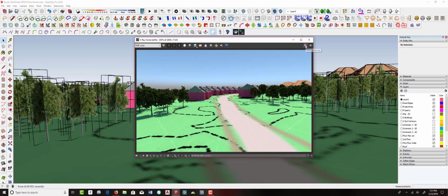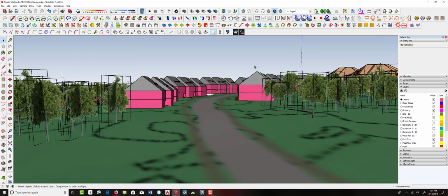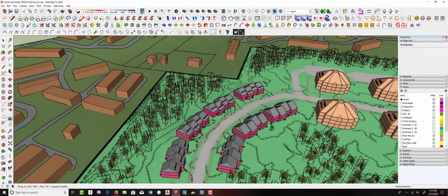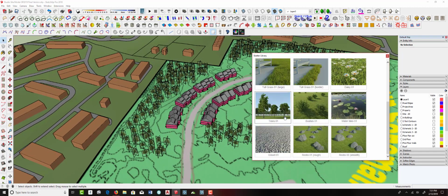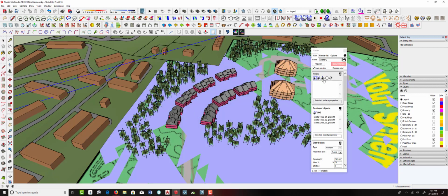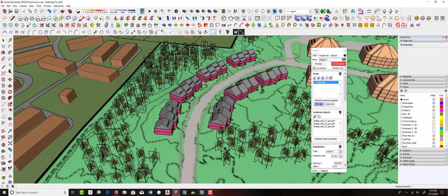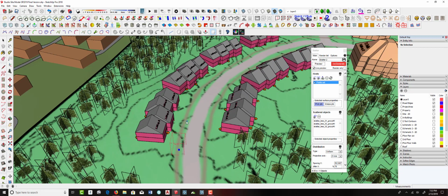And then if I want some individual, let's say our street trees, we want to come in here and add some street trees. We can use scatter for that as well. Load the same library, trees, proxies. Then instead of placing it, we're going to use pick points. So now I can come in here and just say, okay, I want a street tree here, here, here.